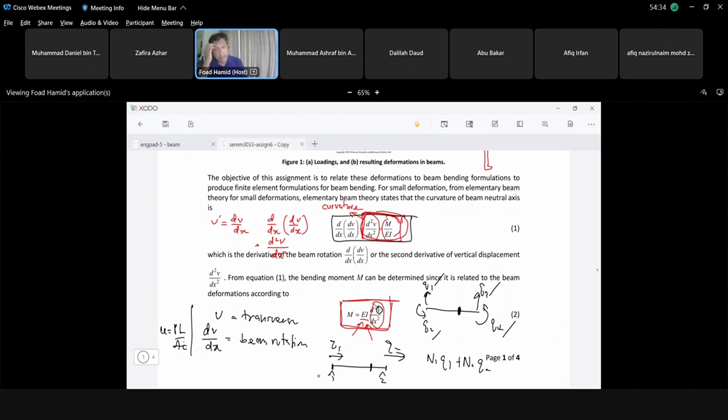For the bar element, we know what Q1 and Q2 are, so we know 2 quantities. In this case, the shape function should be something like A0 plus A1 Z. And this is a linear function. We know that N1 is just (1 minus Z) over 2. So basically our A0 is half, and our A1 is also half. Okay, so that's the shape function.